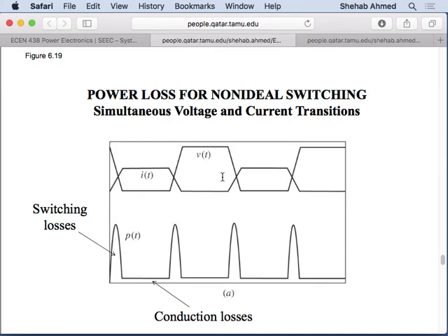How do you select the real inductor? Something that relates to heat and something that relates to physical phenomena. Something that relates to the physical phenomena was the maximum flux that you can push in a core, right? Imax, the maximum current that you can push in there. And then something that relates to the heat that's being produced, it's the I squared, the RMS current that's flowing through the inductor times the resistance of the inductor, right?